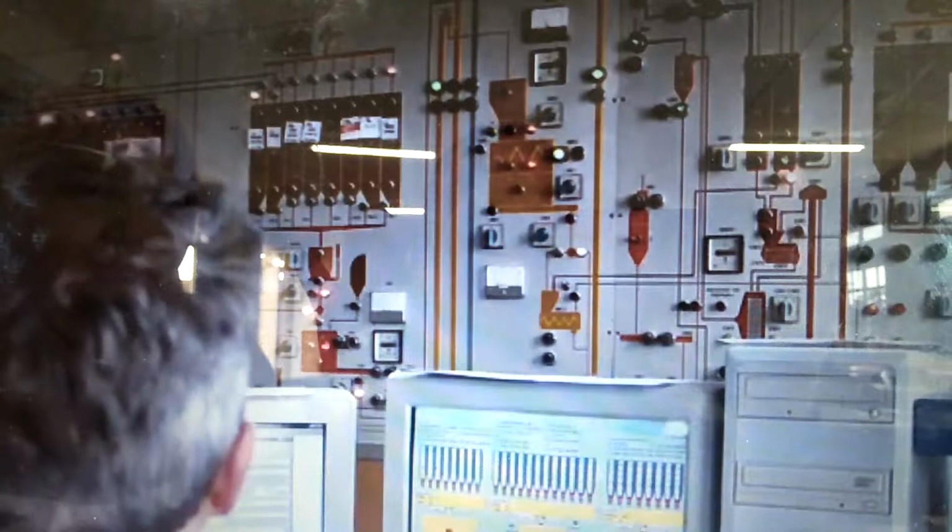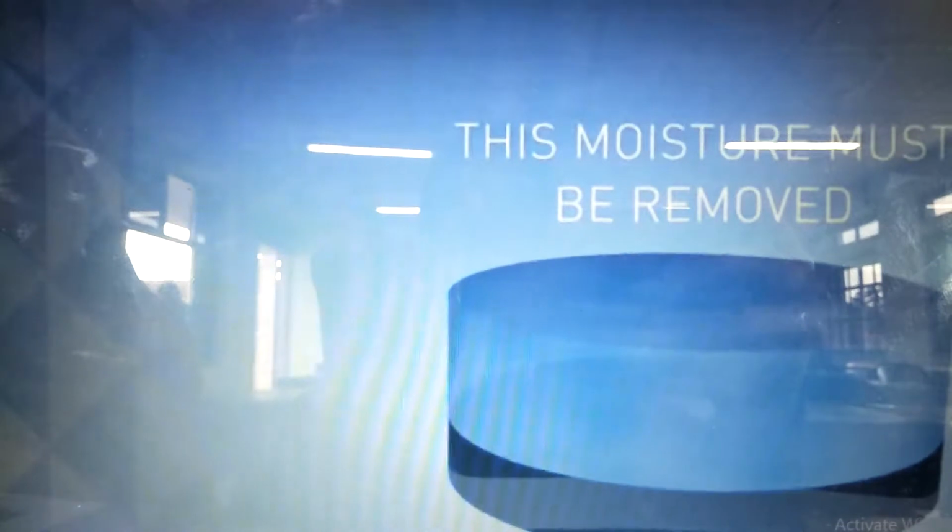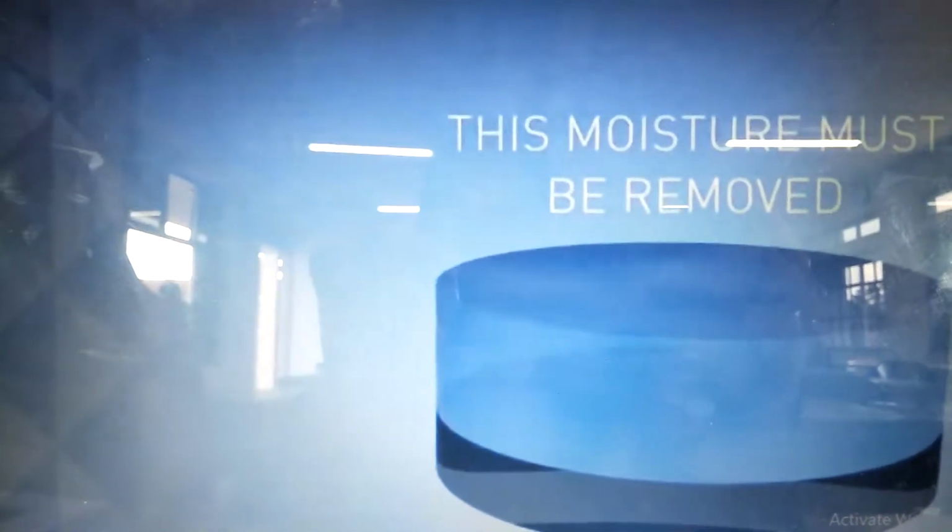Compressed air is an easily storable source of energy which is used throughout the world. Unfortunately, a byproduct of compressed air is heat and moisture. Through compression, the relative amount of moisture for a given volume increases, oftentimes leaving you with compressed air that is saturated with water vapor or containing liquid water. Water and even elevated dew points in the compressed airstream can create a multitude of problems and must be removed